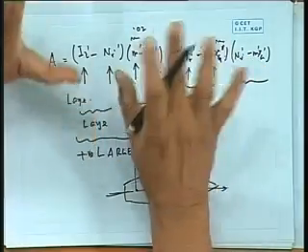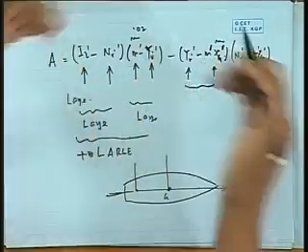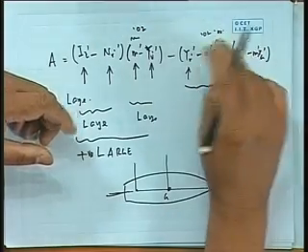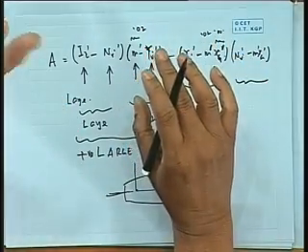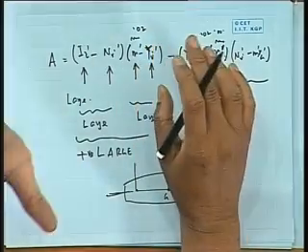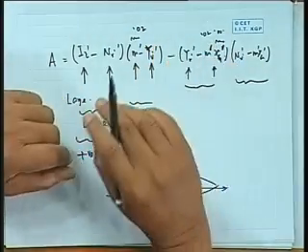Okay, and if you take a non-dimensional value, say this is large, but it will be, let us say, 0.02. This is supposed to be large because you are multiplying with half rho L cube. This is 0.02, but this is going to be 0.00 because it is xg by L, you see, 2 meter by 100 meter or 2 meter by 200 meter. So it is 0.001 something like that. So this becomes much smaller.